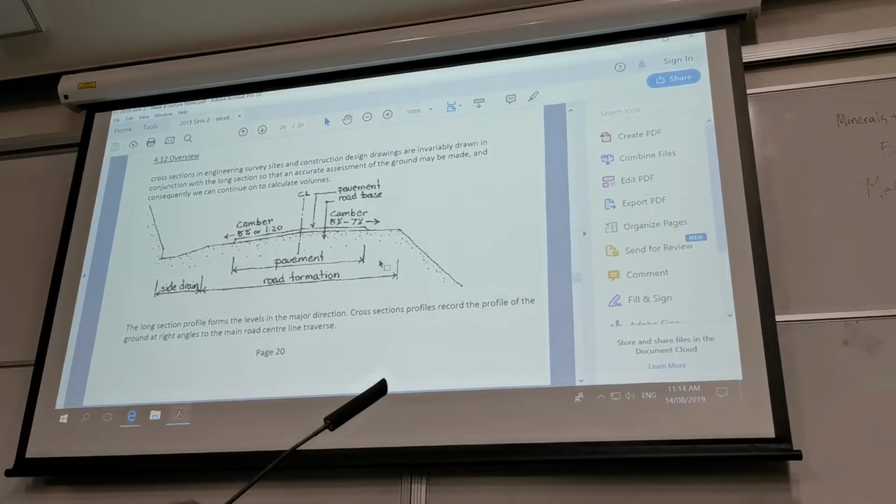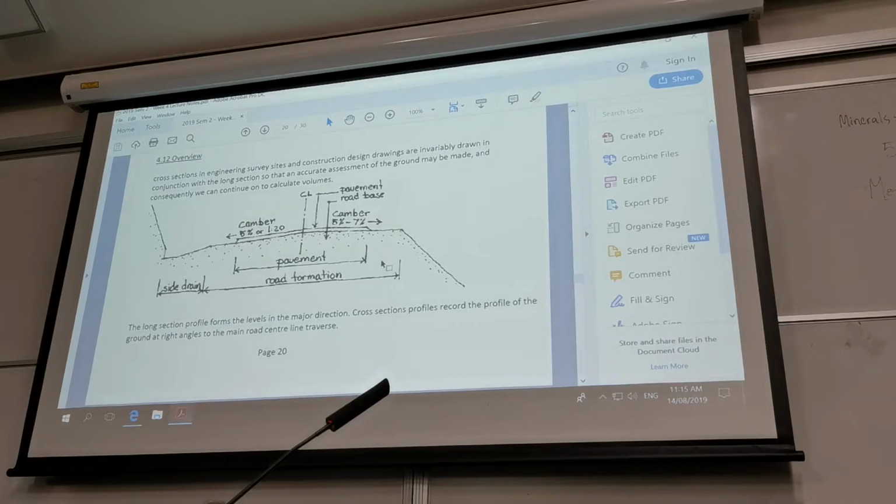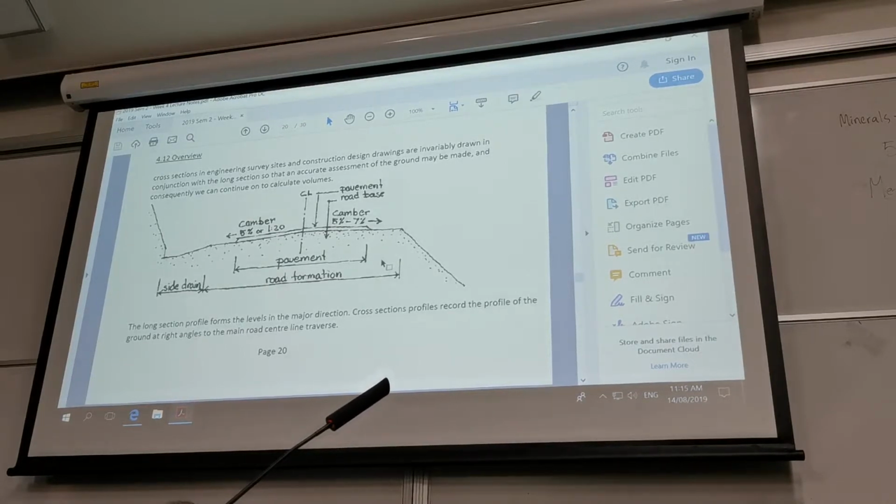Also, there are various engineering tests that surveyors get involved with, where they drop weights onto the road to see how far it penetrates, whether the compaction's good enough or not. The other thing is the positioning of the road. It's very easy to end up making roads wider or smaller, and once again, surveyors on roading jobs are there the whole time, keeping an eye on all that sort of thing. So they need a very good background in these terminologies.